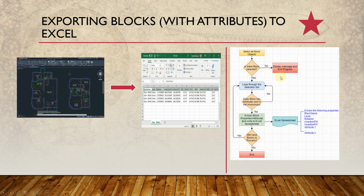And our flowchart will flow something like this. We just select all the block objects and loop through the selection set. Then we are going to validate if the block has attributes and it's not an anonymous block. So if the block has attributes, then we're going to extract these properties. Again, the block name, layer, the rotation angle, the insertion point X and Y, and the list of attributes.